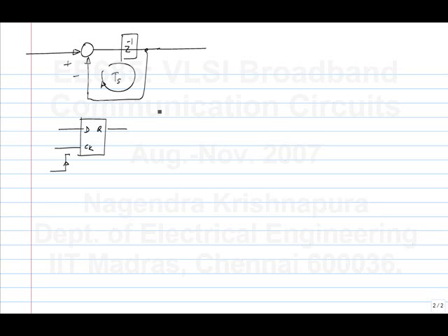Okay. So if you try to make such a delay, a flip-flop can be used as a delay element in some cases. We'll come to that later. If you do make such a delay, you have an extra delay of e to the minus sT, where T is a significant fraction of Ts. So typically you can't make IIR filters very well, especially at very high speeds, because you cannot close the feedback loop. The feedback loop can have excess delay, and particularly with the emphasis on high speed implementations, you can't do this. If it's at low speed, that's okay.